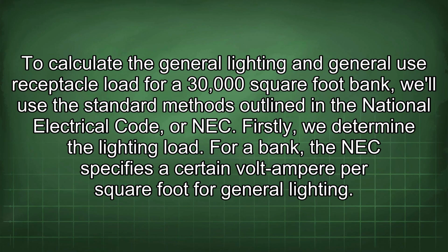To calculate the general lighting and general use receptacle load for a 30,000 square foot bank, we'll use the standard methods outlined in the National Electrical Code, or NEC. Firstly, we determine the lighting load.